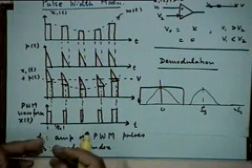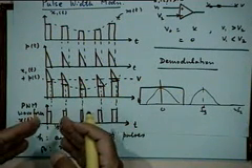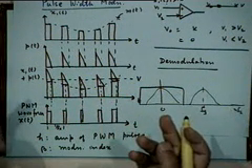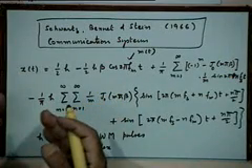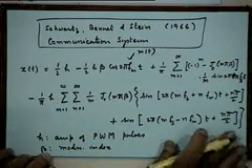So when you choose a maximum pulse width to be equal to 1 by 2 fs, beta is said to be 1, right? So that's like 100% modulation. So beta is this parameter. If you choose the maximum pulse width to be less than 1 by 2 fs, beta is suitably scaled down appropriately, right? So that is what beta is. It's a measure of modulation index. Now let's see whether there is any method in this madness.